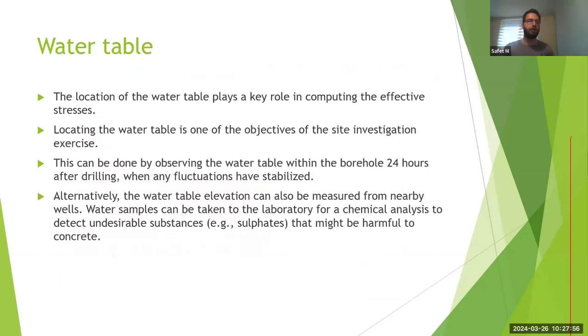One really important thing in the ground is also the water table. The location of the water table plays a key role in computing effective stresses. Locating the water table is an objective of the site investigation exercise. This can be done by observing the water table in your borehole that you drilled 24 hours after drilling, when everything is stabilized. Depending on the structure, if the project is long term, you're probably going to monitor your water over the year, just so you can see what's the maximum groundwater level that you can expect.